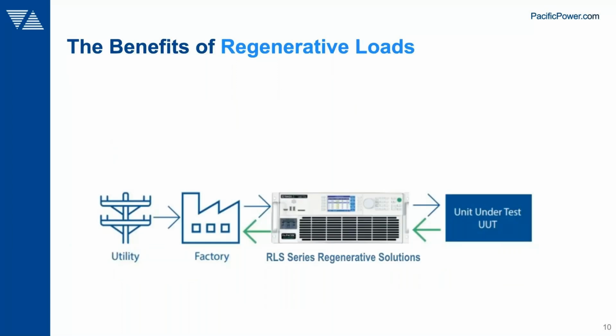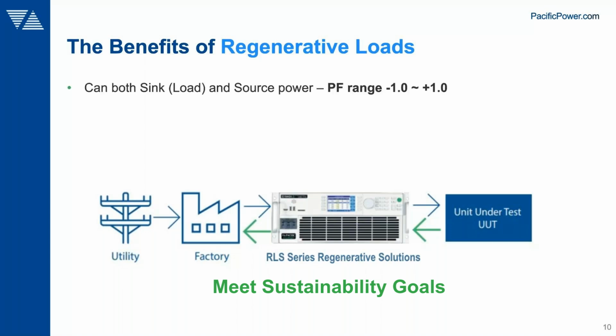So the benefits of regenerative loads in particular are obviously in the area of energy savings. In the case of a regenerative load, your power is basically converted back to the utility instead of being dissipated into heat. That also means they have the ability to cover a wide power factor range, from both plus and minus 1.0.